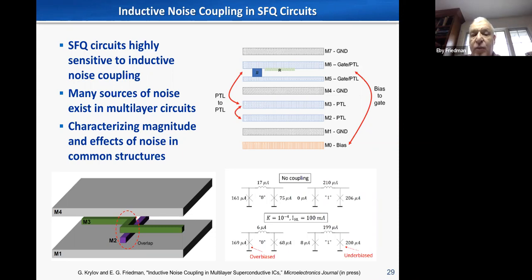and design with inductances. And part of the issue, as I show down here, is you have inductive loops on purpose. This is how you store a state, which I should have mentioned earlier. You have a Josephson junction here, another one here, and an inductive loop. And you basically store a state, in this case the one state, and it can stay here forever. Or there's no pulse. But the point is that as long as it's maintained cryogenically, you maintain that state forever. And you worry about coupling between these various points. And so there's been a lot of work in this area.